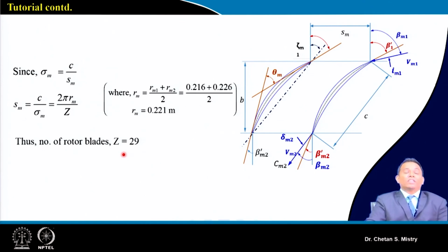Now the mechanical engineers will have their own constraints in accommodating the number of blades on the hub. Suppose our hub diameter is small, and we are planning to fix a larger number of blades; it may be very difficult for them to design the slots. Okay, suppose you are considering a blisk kind of configuration; there, in order to do machining, it may be possible that the tool may not go inside. So here also we have a constraint.